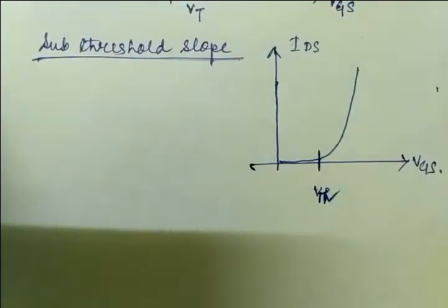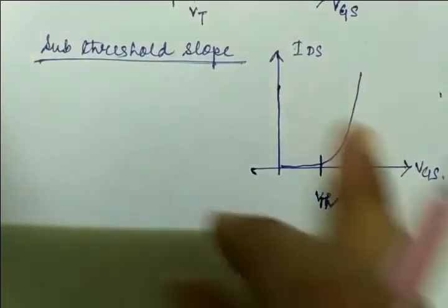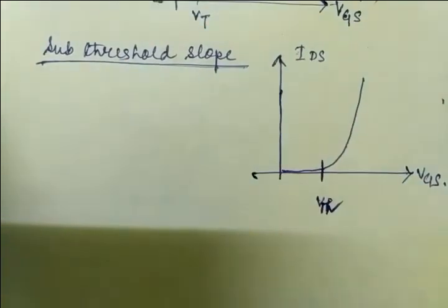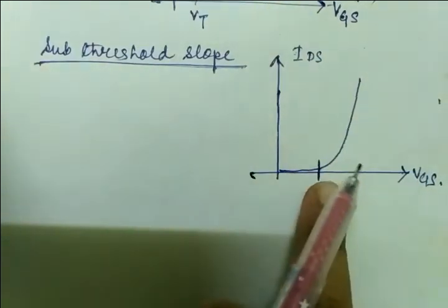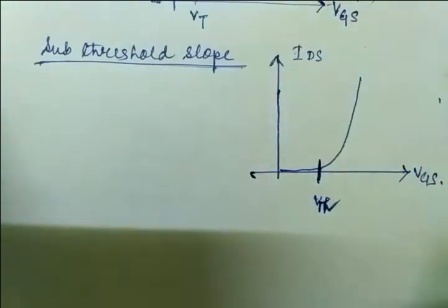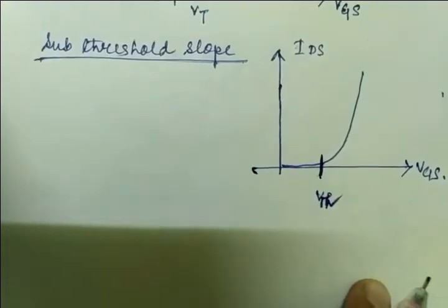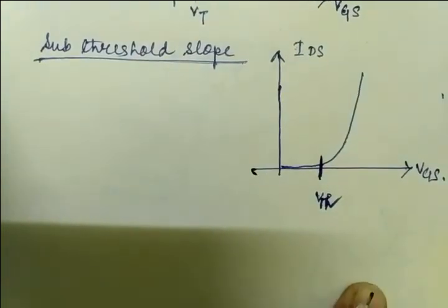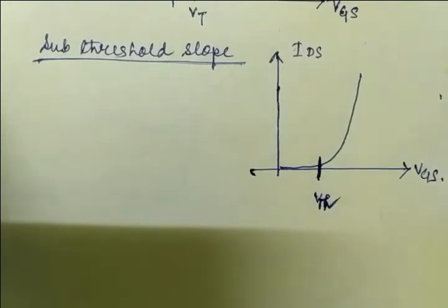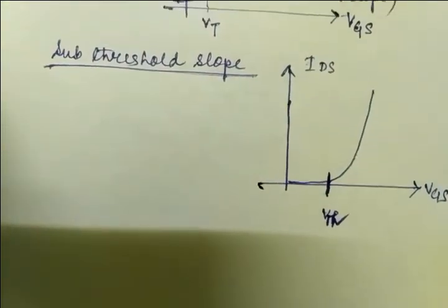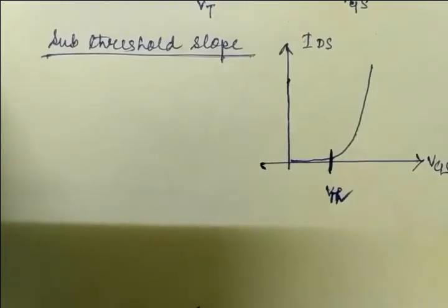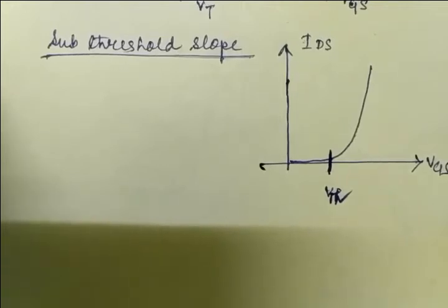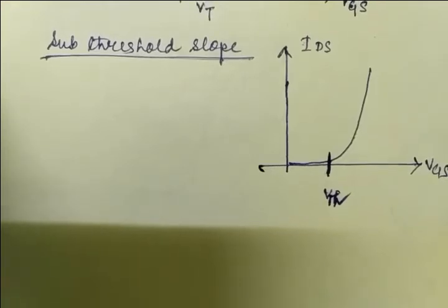VTH, right? This is the threshold voltage. From this linear characteristics curve, we all know that the current increases exponentially from a certain point. I think you all have the threshold voltage concept, because you have already solved examples by considering the threshold voltage. From the previous Google Meet, you can also find out what the threshold voltage is, what its effect is on drain current and gate voltage, and what the related formulas are. So you all have the concept of the threshold voltage.